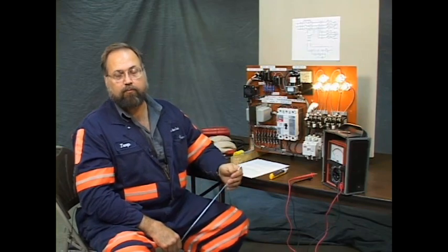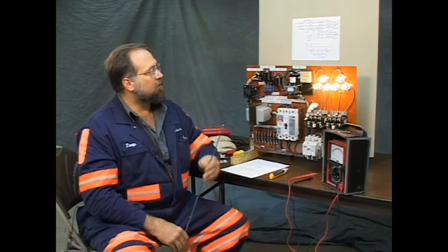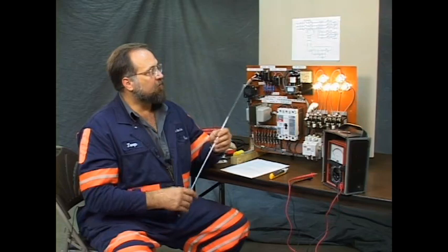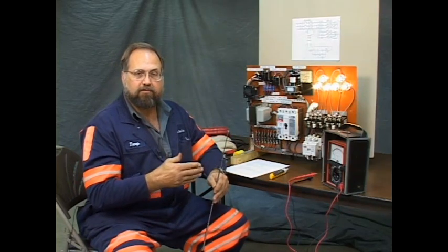It would restart by itself. That's undesirable in machinery controls. So we have a normally open start switch. We're dependent upon a holding circuit through interlocks, and if we have an overload, anything stops, it reverts to its stop state, its normally open state, and it has to be restarted manually.